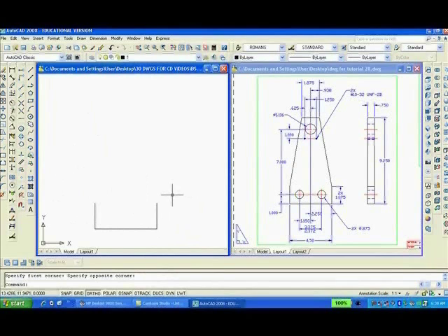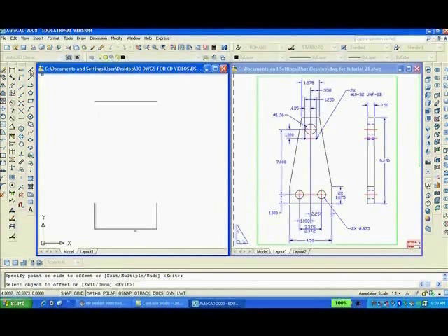I think the next thing I'll do is to offset, enter, the total height, which is 9.25, enter. Then probably we'll draw a line from the midpoint of the bottom here straight up,